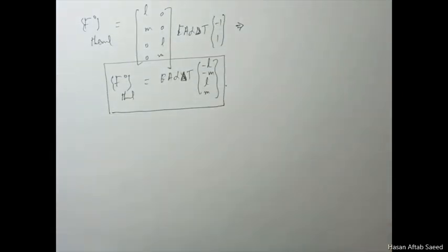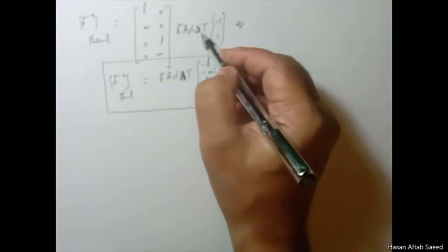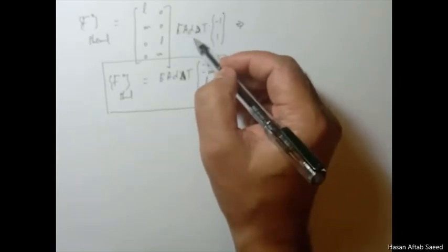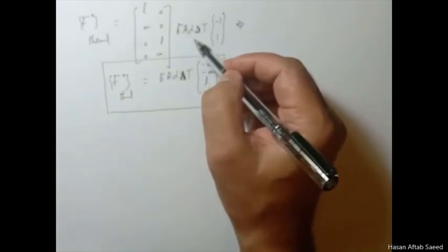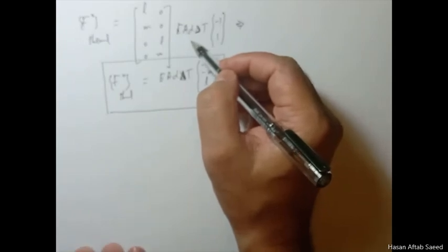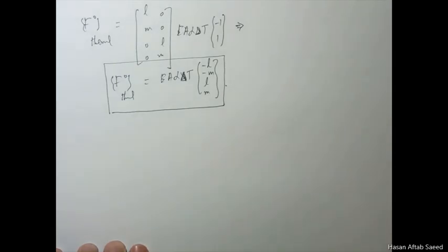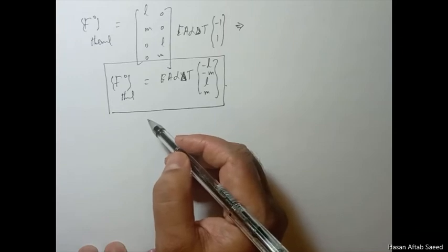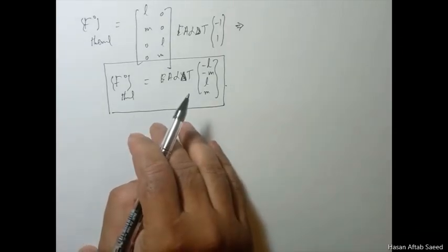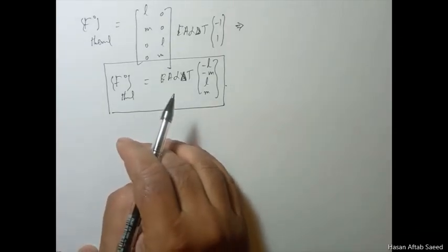And one thing you need to always remember, again, like we did last time, is that whenever there is a delta T involved, there's a change of temperature, and then there's a force vector because of that. The displacements you get are the total displacements, because of the thermal as well as the mechanical part. So the strains calculated will be total strains. You have to subtract the thermal strains from those values to get the stresses. We'll deal with that when we take up a couple of problems using the theory that we have just derived.